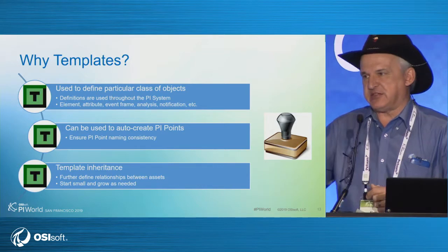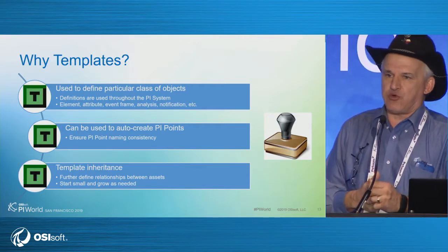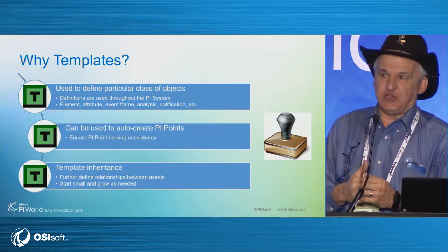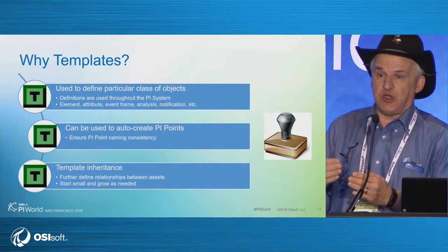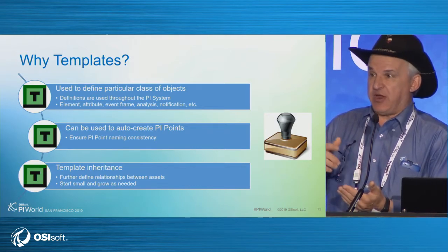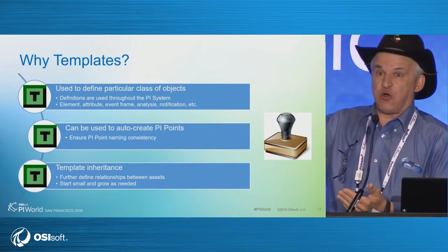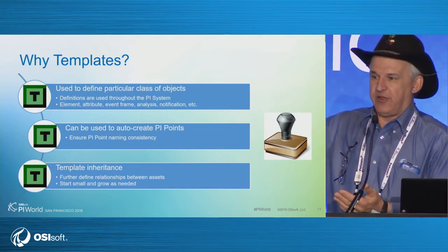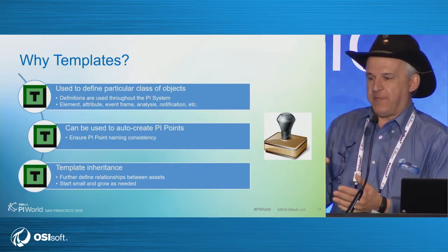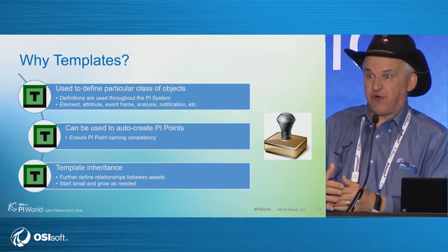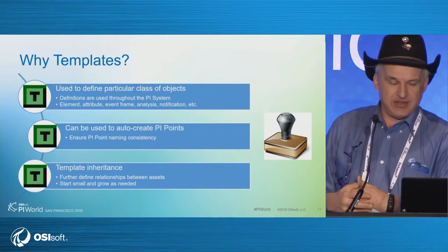The good benefit is that some of you may or may not use it, the auto-create PI point. That's not as useful for people who are not evergreen, but it's useful when you're doing calculations, new things. So you now standardize a methodology for naming. I'm going to create tags from calculations that I'm going to store for efficiency and make it easy, deployable. And I'm going to create a naming methodology so that I have a standard now, at least for my outputs. Right? That makes it easier.